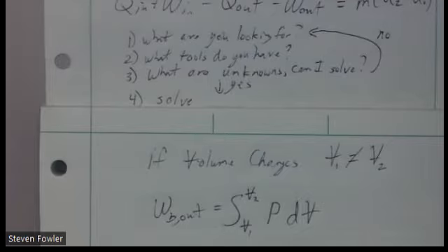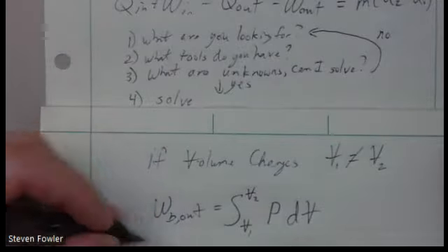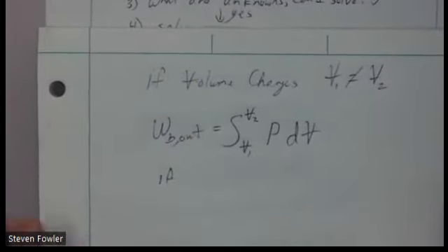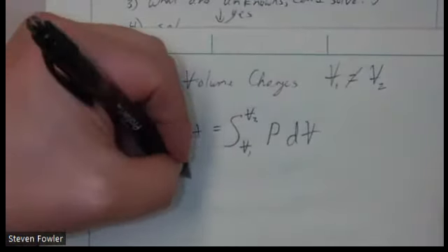So again, work is done by a force. In the case of boundary work, what causes or applies that force is going to be pressure, either internal or external, or the difference between the two. And the distance traveled is going to be determined by the volume change. So the work term is caused by a force. We've discussed before if it's compression or expansion, the difference there, right?